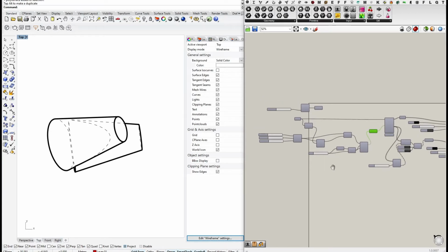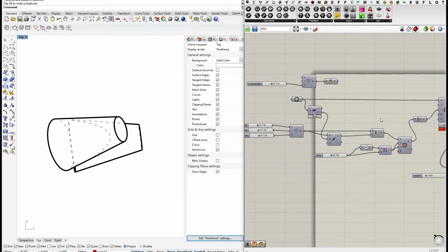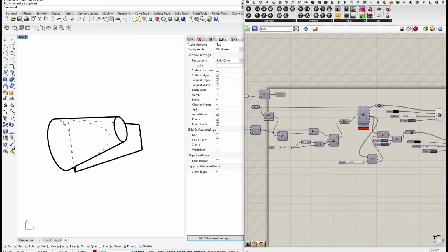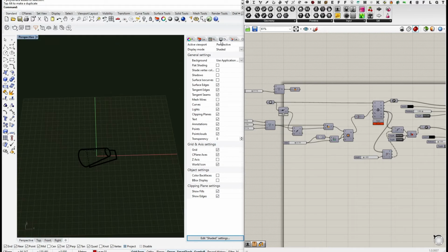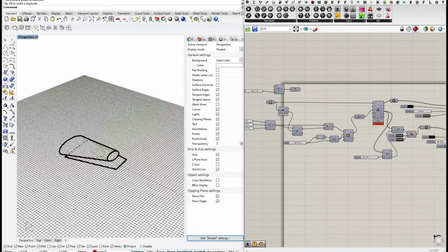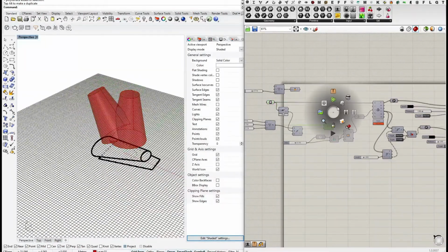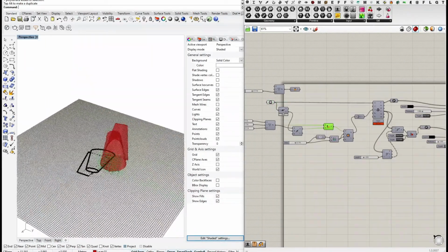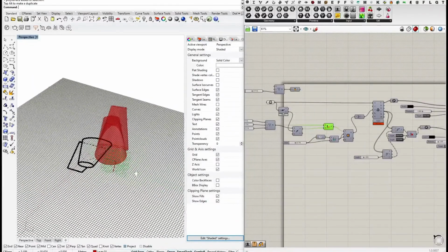And one very quick trick is, because we already have the geometry and because we set up our viewport through a plane, to insert a background behind our 2D drawing geometry. I will do this in perspective view for a second so that you see what we will do. We have our Make2D drawing, which is flat on the ground, and I will quickly turn on our geometry again, and our view plane from which we are currently doing our Make2D drawing.